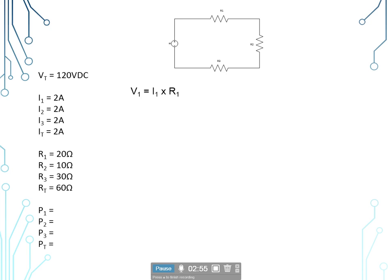Now I know our current remains constant in a series circuit. However, we use a specific current for the device or the component that we're talking about. That way we don't get confused when we switch from a series circuit to a parallel circuit or to a combination series parallel circuit. And so we're going to take our I sub 1 of 2 amps times our R sub 1 of 20 ohms to get a 40 volt drop on that first load.